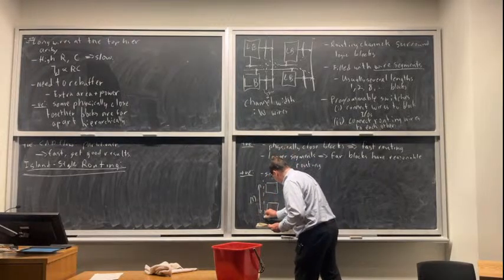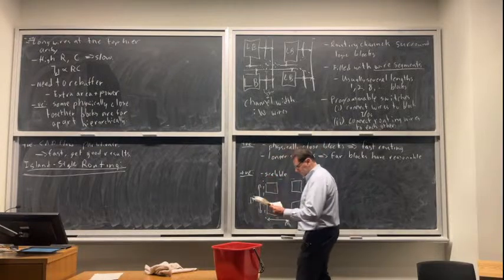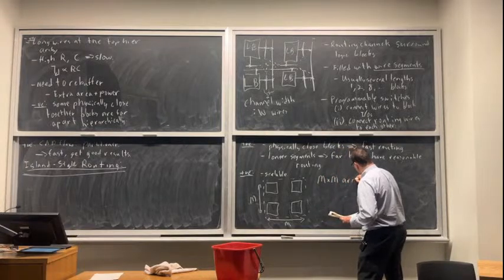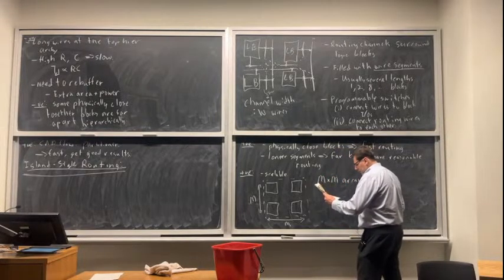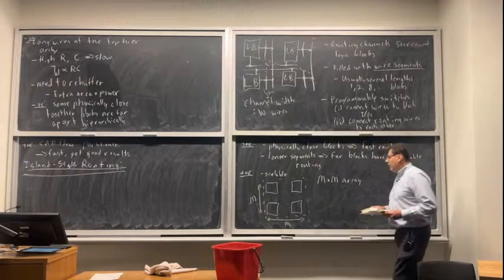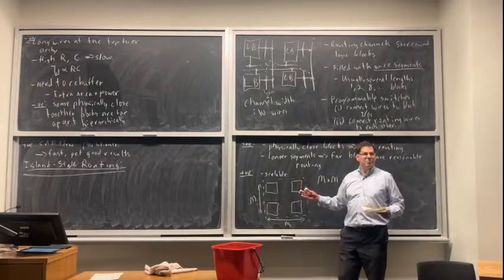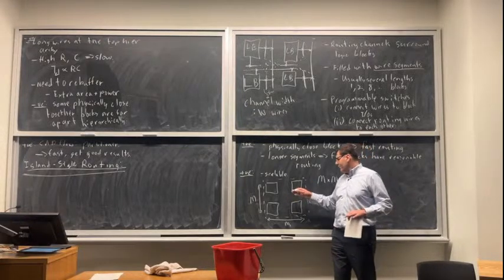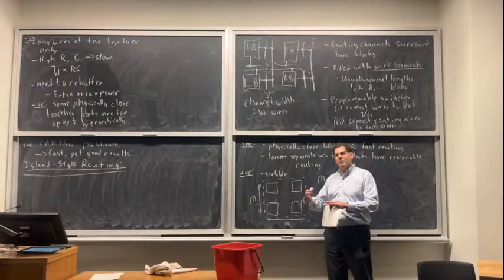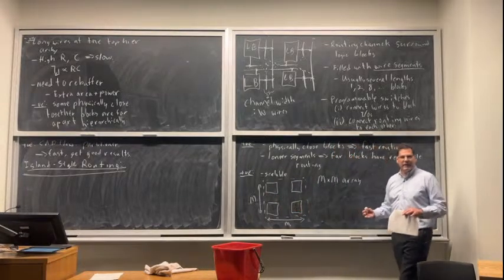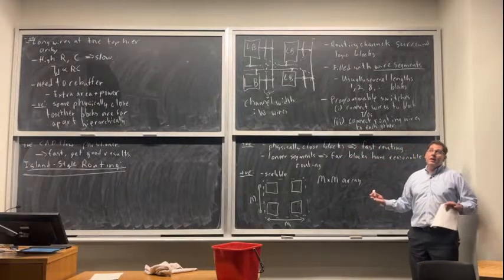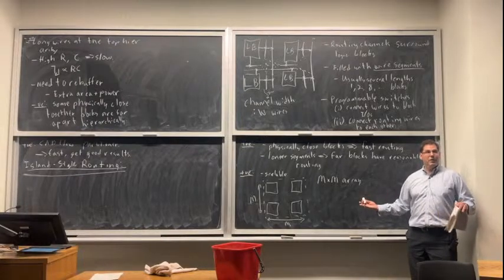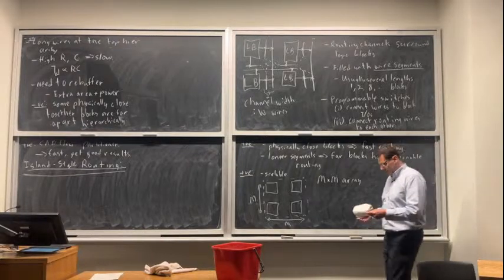Okay, so that's what you're considering: an array that is m by m. I'm basically going to change m, gradually making this array bigger, because I want to see what happens to how much logic I've got inside this array and how much wiring I need inside the array. That gives me a sense of whether this is scaling well, or whether I'm having to increase the wiring way faster than the amount of logic, which would indicate this doesn't scale very well. It's going to get really inefficient if I make it big.